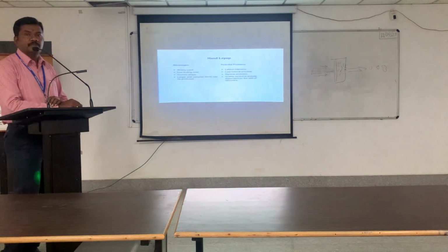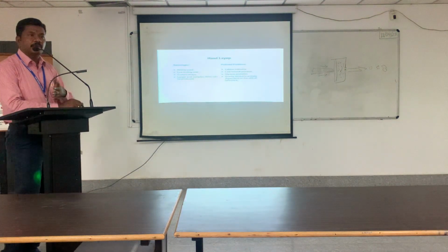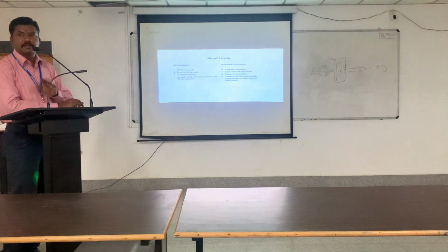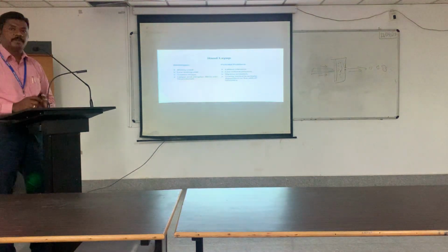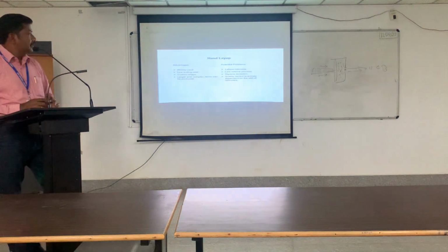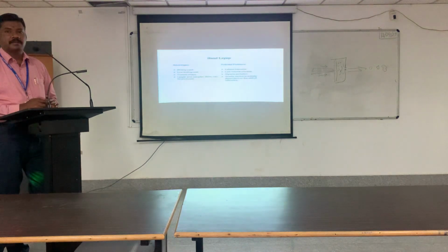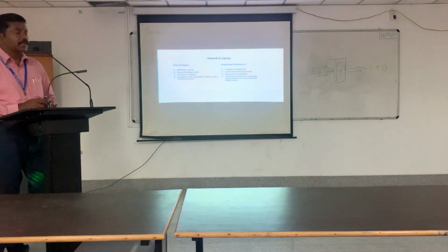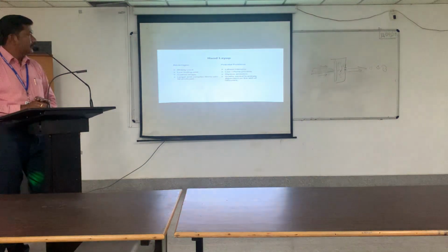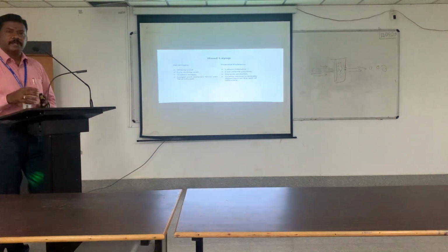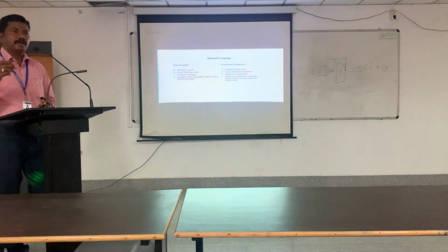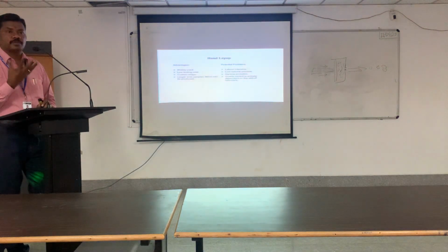Labor intensive. Everyone cannot make the composite very easily. Some kind of experience should be needed, and skilled labor should be needed. Skilled laborers will demand more cost. Okay. So labor intensive, low volume process, styrene emission. Some of the matrix materials, while adding some additives, will create some amount of fumes.